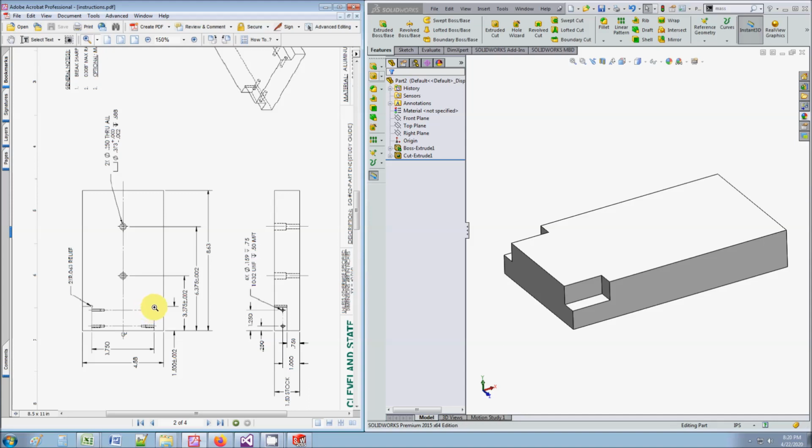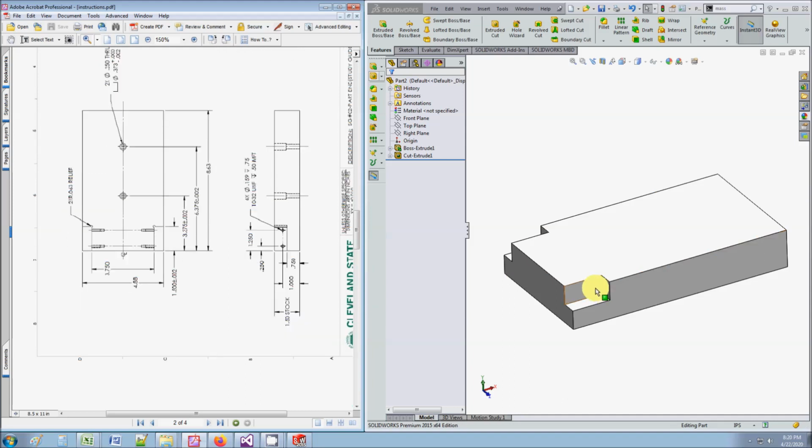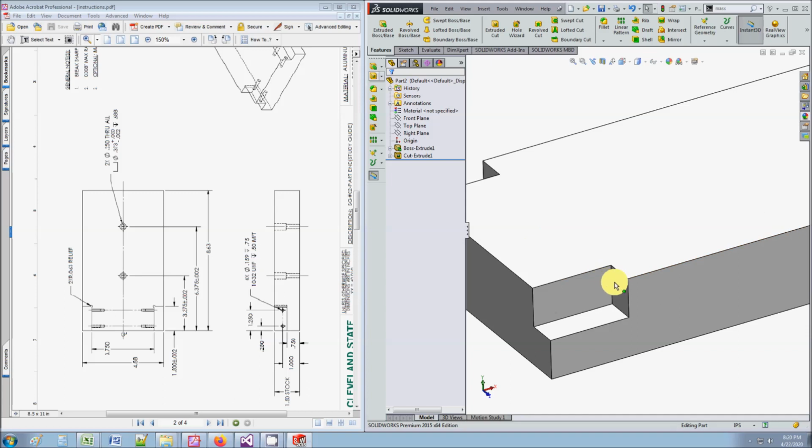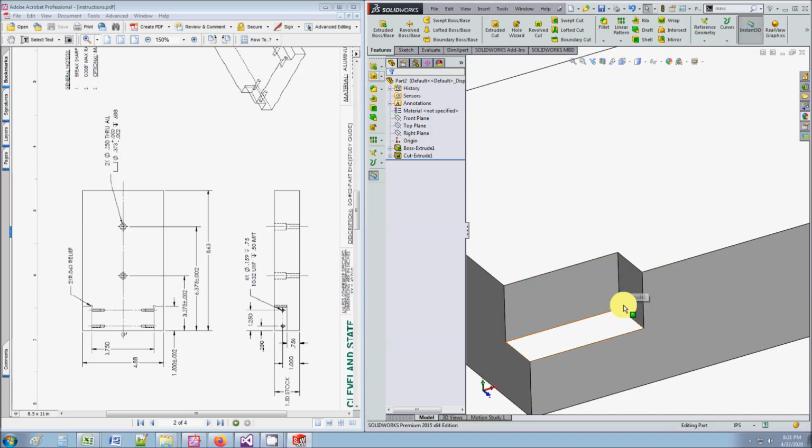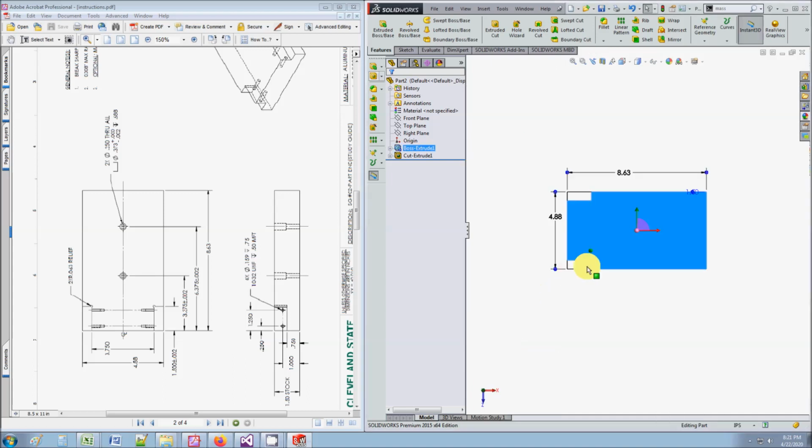Next thing I'm going to do are these reliefs. See those reliefs? If you looked at one of the slide decks in designing for machining, the reason we have a relief there is because it's very difficult to machine a square corner like this on 3 planes. On 2 planes it's fine, but when it's on 3 planes, it's very difficult, and I talked about that.